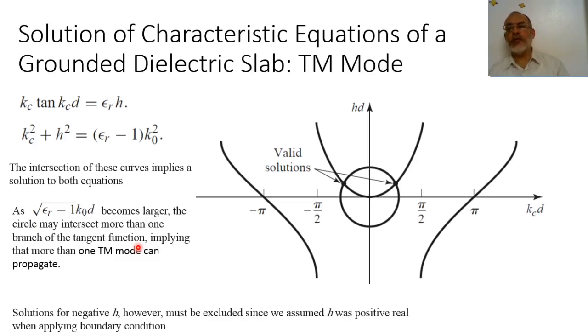In other words, at any frequency, the grounded dielectric slab supports the dominant mode, or the lowest cutoff mode, of the surface wave inside the grounded dielectric slab. So the cutoff frequency of the TM0 mode is 0. This means that we always have a transverse magnetic surface wave mode in a grounded dielectric slab.